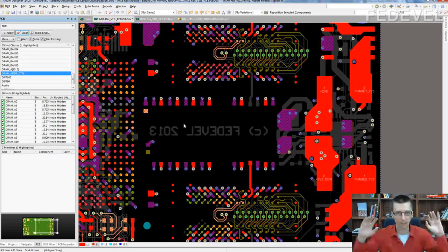I read it a long time ago in an Intel design guide. I use it all the time and it helps. I've seen a memory which was not routed by this rule. Some of the tracks of one group were routed on the top layer. Some of the tracks, same group, were routed in the middle of the PCB. This interface didn't work reliably.